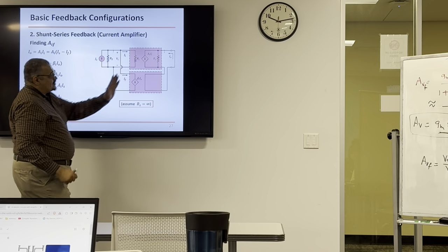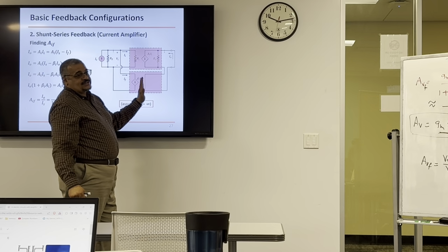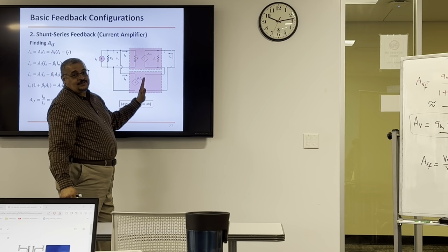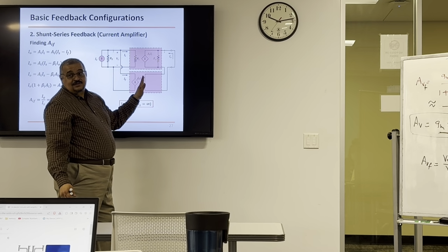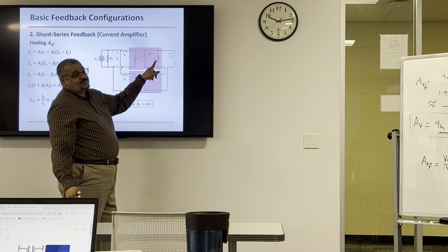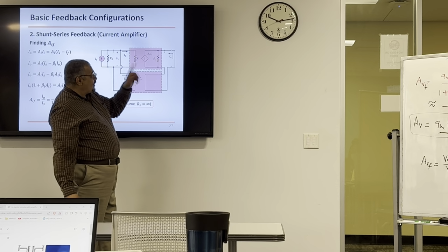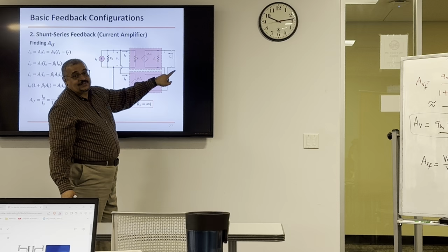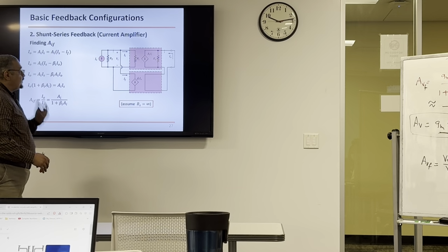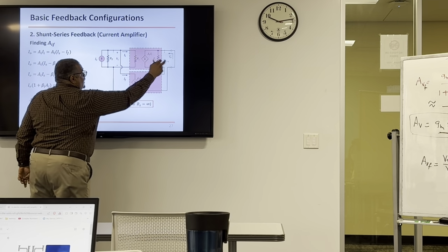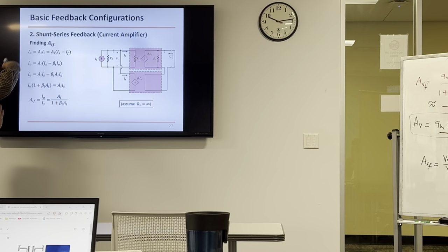If you have a resistance in parallel with a short circuit, what's going to happen to the current? You think the current will leave the short circuit and pass through RO? No, all the current will go to the short circuit, because it's a highway, right? Okay, so IO is the same as AI, and with the same direction, right? So there's no negative sign here.